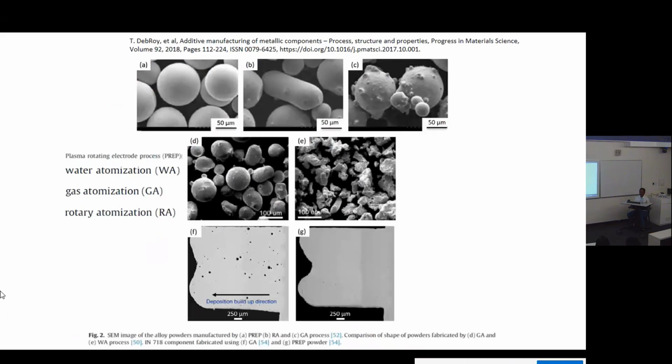If you involve melting, there are a lot of other issues that come into play. Certain metals will only dissolve in certain other metals in desired proportions, whereas with cold spray, you can add as much as you want.